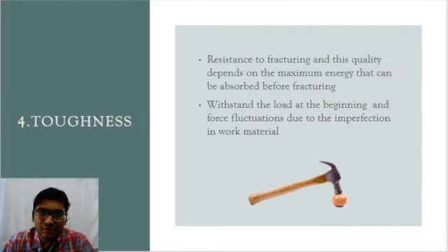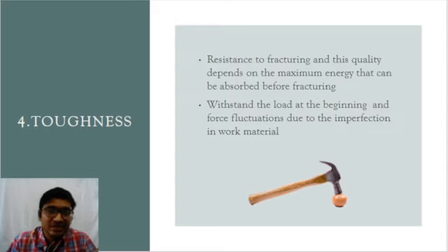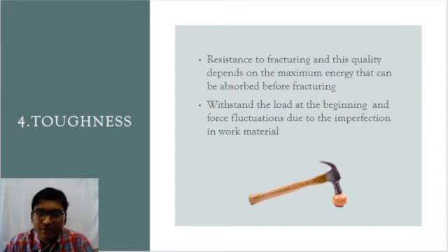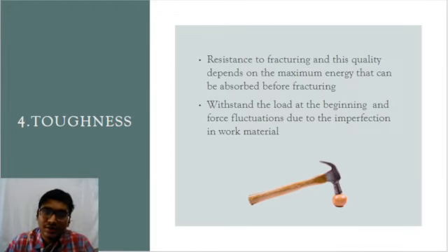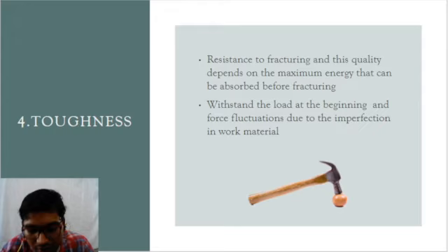For the cutting tool material, the toughness must be higher, so that it can withstand the load at the beginning. When we do machining, there is an initial and sudden load when we make contact between the tool and the work material. The load must be withstood without the breaking of the tool.